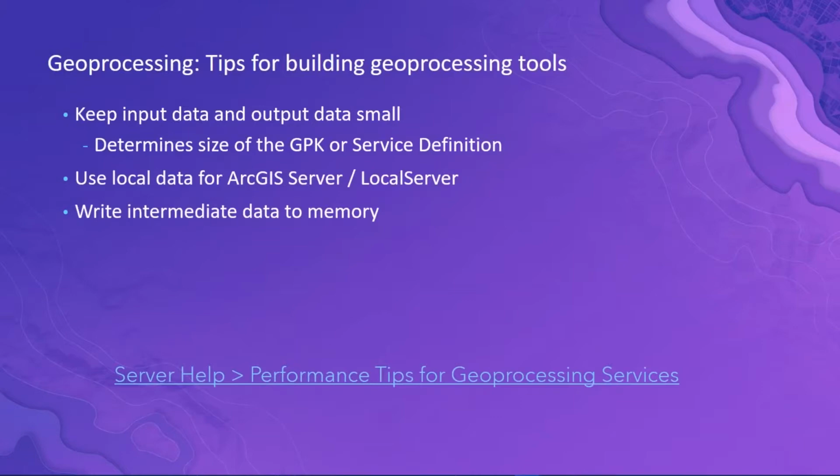Also within that workflow, as you go through each step within your script or that model that's being run, make sure you write that intermediate data to memory. You don't necessarily need to write that to disk. We have a way to use the memory of the device in order to do that. Also, there are standard ways that we provide for you to add attribute and spatial indexes to your data. So make sure you do that. That'll help with the querying and the accessing of your data that you're using for the analysis.